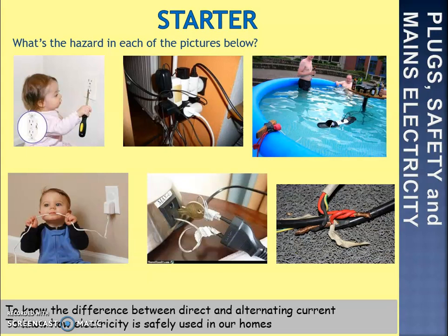Bottom middle, again, that plug is not designed to be used with that plug socket. So they've adapted that with a key and another wire. That's exposing a lot of bare wires. Electricity there would be very easy to give someone an electric shock. And finally, the bottom right, there are bare wires exposed there. If there's a current going through there, it's very likely to cause a shock with anyone who would touch it. Maybe even a fire with any area around it.